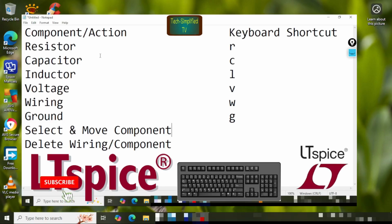Next is select and move component. That means whenever we are selecting any component and changing its position or changing the name of a component, we can use this key. To select and move, we use M. And you can see it is small m. That means from the keyboard, we will hit the M key without touching any other key.